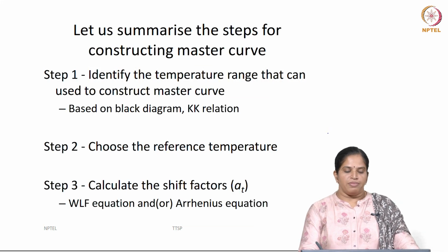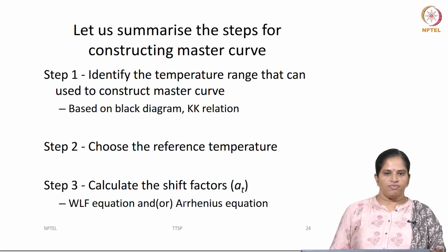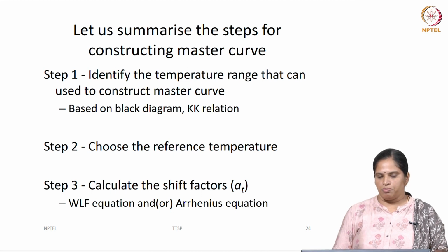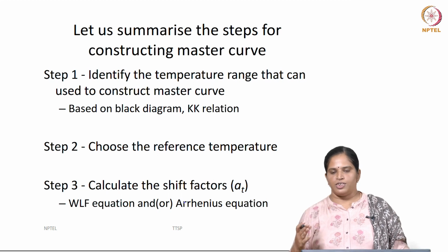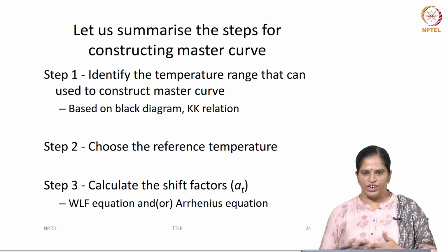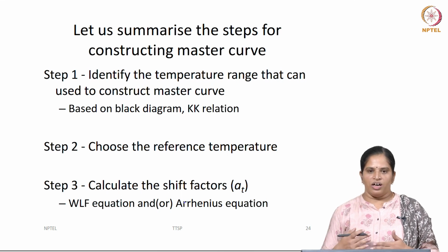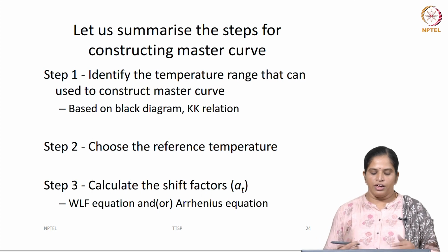So, now let us summarize the steps that we use to construct a master curve. First, you have to do an experiment: a frequency sweep test in frequency mode, or a relaxation test or a creep and recovery test at different temperatures. Now you have different temperature data as a function of frequency or as a function of time.